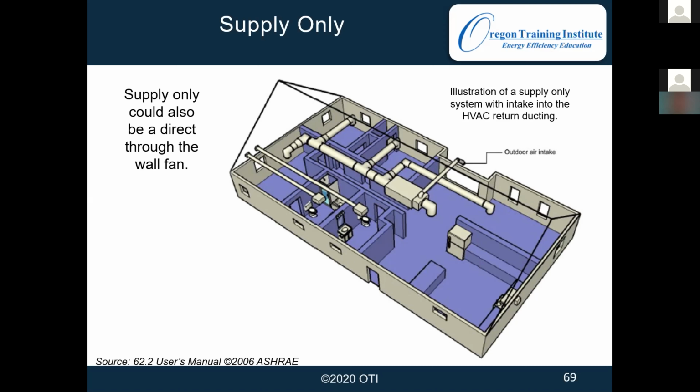So this would have the effect of pressurizing the home. If anything was backdrafting and those exhaust gases were coming into the house, this would help push them out and help prevent that. Of course, there is going to be an energy penalty with that, blowing cold air in.